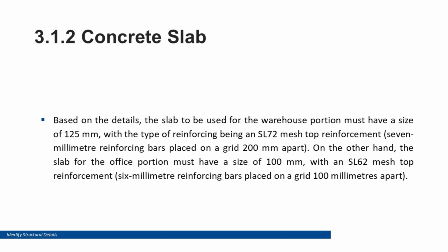Slab drawings are often supported by sections showing the layers, vapor barriers, hard core, reinforcement placement, and edge beams. Reading slab details is crucial for correct concrete ordering, setting out, and supervision during pouring and finishing.